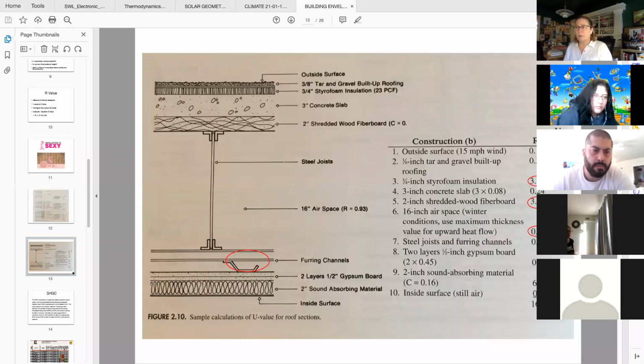I can't remember if it went from 2x6 to 2x8 or 2x10 maybe, but adding in more insulation in their walls and going with a higher performing glazing cut the load in half. So it went from like 12 tons of AC down to 5 or 6 tons, which makes a huge difference, not only in the installation cost of the size of the equipment, but in the operational cost over the lifetime of the building.